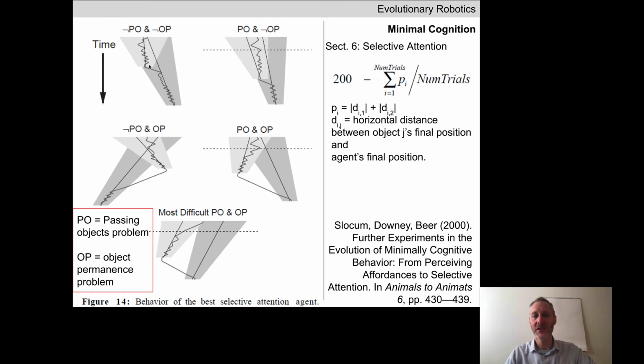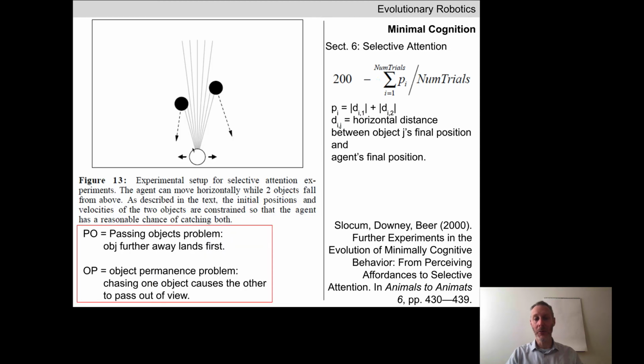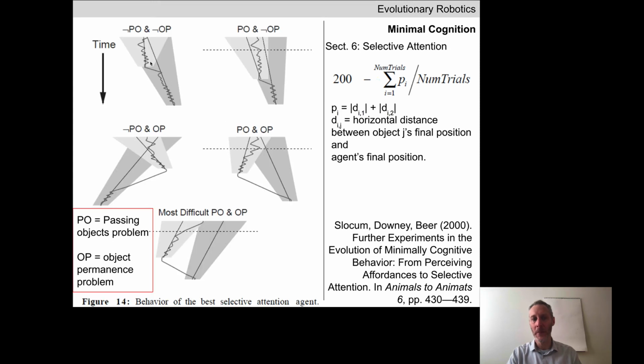As Logan mentions, it's the field of vision. So remember that the robot has these 7 proximity sensors. Obviously, as the objects start to move lower in the panel, there is a narrower field of view that the robot has. It's easier for the object to pass outside of the robot's field of view, which is represented by the parallelogram, this narrowing gap.